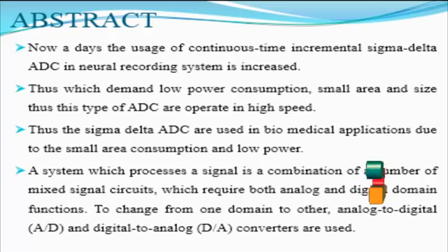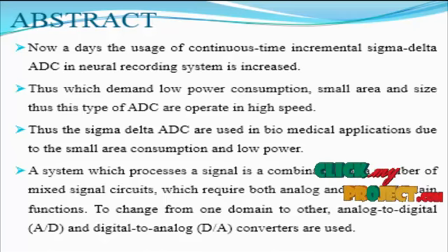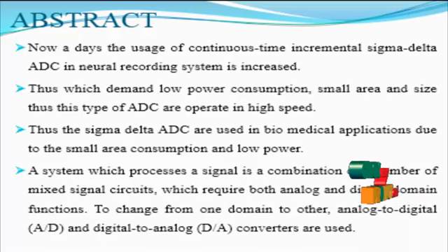Due to the benefits granted by technology scaling, both operation frequency and energy efficiency are improved in highly digital ADC architectures, which allow very energy efficient designs, especially for circuits consuming mainly dynamic power. Both intrinsic parasitics and supply voltage are shrinking, which implies a drastic improvement in power consumption. On the other hand, advanced nodes are limited, while an architectural optimization can be more general for different scenarios under various technologies.